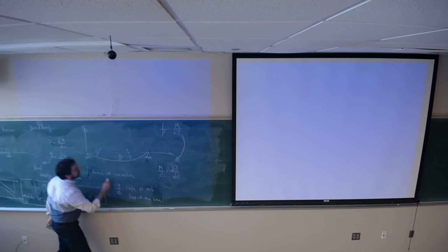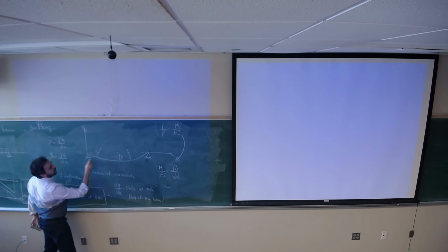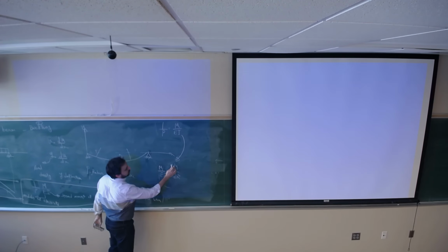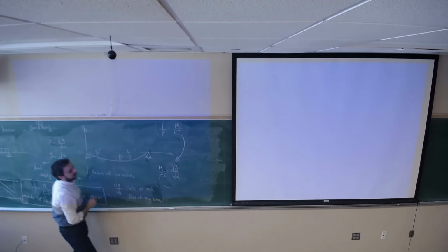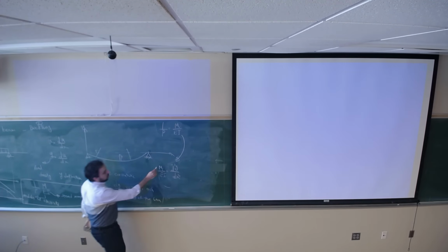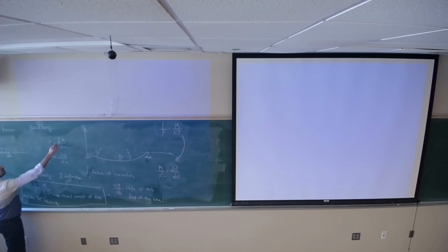If I ask you to find the slope at each point of the beam, dy over dx is going to represent that. So the second derivative of y with respect to x is going to equal M over EI. Now, if I differentiate the bending moment with respect to x, I can get the shear force.